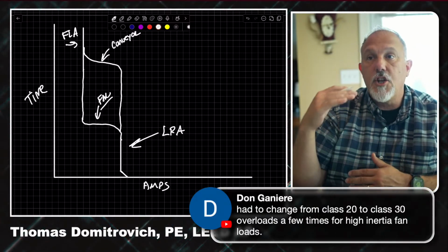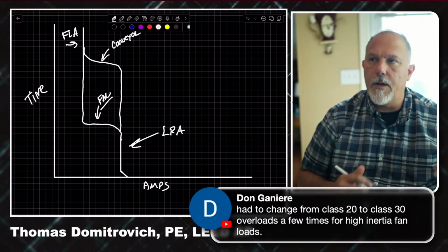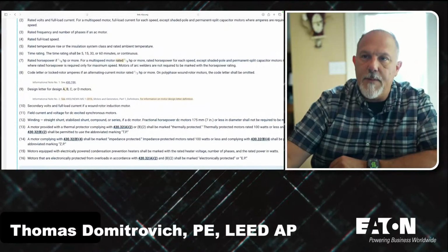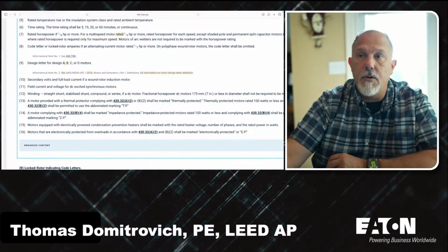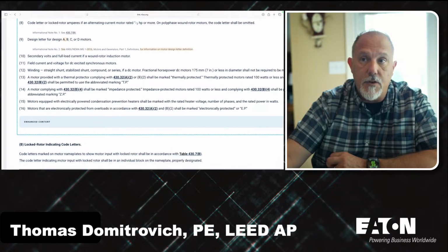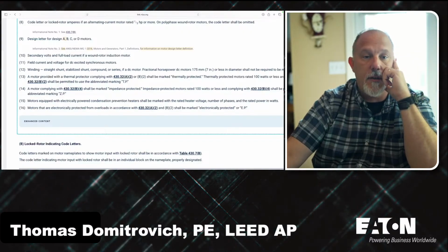The code letters give the locked rotor amps, or the actual locked rotor amps will be on there as well. I happen to have my design A, B, C, or D motors. This is going to be your torque speed curves, secondary volts and full load current of a wound rotor, field current and voltage for DC excited synchronous motors, your winding, straight shunt, stabilized shunt, all that good stuff.